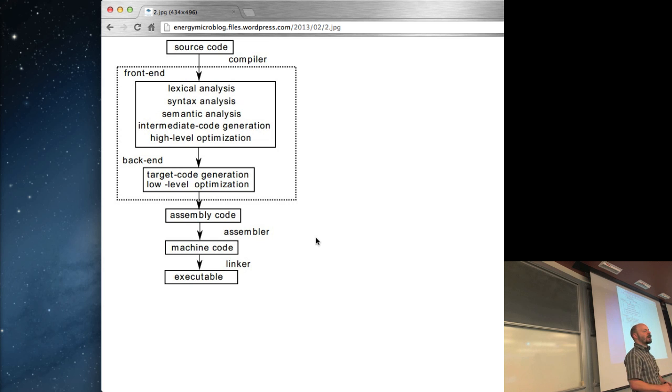For example, we just talked before about how can we wait for 1 second, right? Well, so it's very easy. You take a variable, write a number in it, and then just subtract 1, compare to 0, subtract 1, compare to 0, until you have done, for example, 50 million iterations of it, which on a CPU that runs at 100 megahertz, 2 instructions per cycle, so 50 million cycles would be 1 second. Now, an optimizer would come in and see that you are just waiting there. That's stupid, right? That's not optimal. So it just removes the whole busy loop, and, well, gone is the second of wait time.